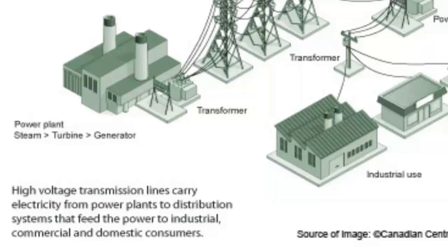Distribution assets are those wire assets downstream of the high voltage network and connection assets. Traditionally, distribution assets include stations and single circuit lines or feeders, which are operated at less than 50 kilovolts. Typically, distribution stations have 2, 3, or 4 feeders to distribute supply to retail customers and end users.